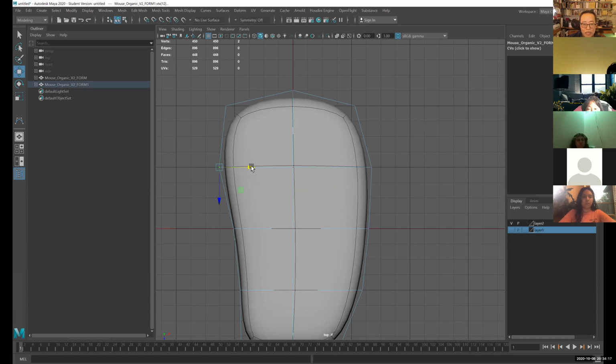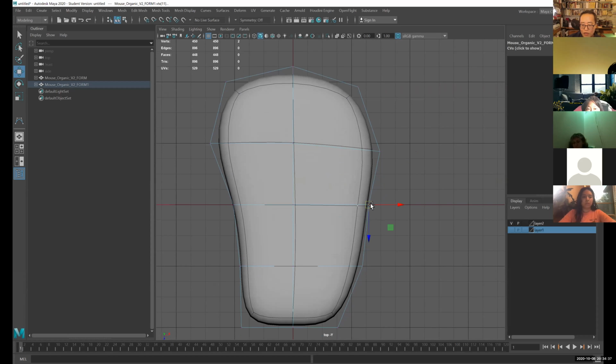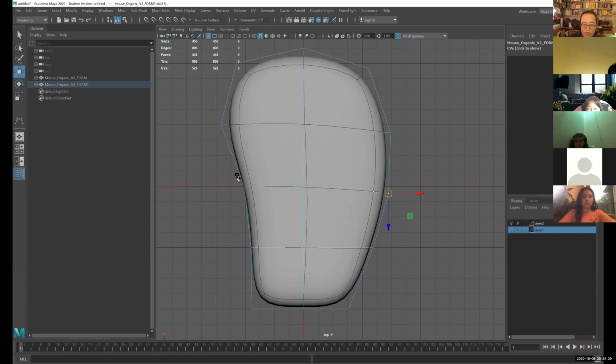So what I'm doing here is that when I want to select the vertices, I do a left mouse click to select, and then I do a middle mouse click to move them around. Okay, and then you don't need to use the arrows. You can click and drag on the square and move it all over the place, if you want, which is fine. So yeah, you can go off of this plane. You're not limited to any flat planes or anything like that.